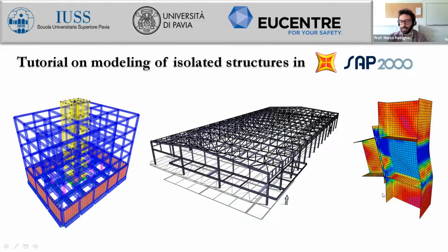And you see that this is a model which analyzes the local level of a structure, so just a beam column joint, by considering, for instance, steel profiles, and instead of having just a frame element for the steel profile for a beam element, you are actually modeling all the plates which compose the profile of the column, and also the same for the beam.